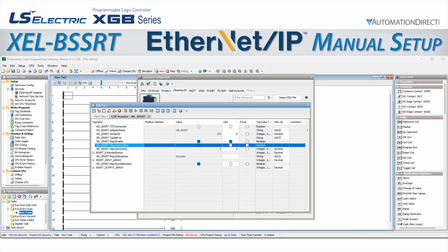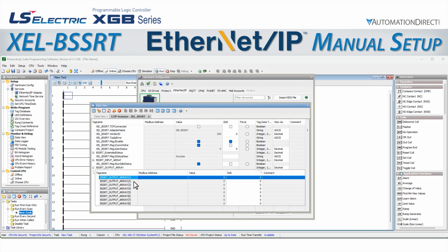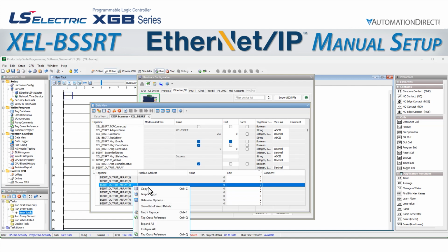We go back to Productivity Suite and maximize our output array. Remember that it's the third address we're looking for, and the productivity software starts its array element number at 1, so we will actually use element 3, not element 2, to control the TN32A. Productivity Suite also has a cool feature to allow us to look at the individual bits within a word. We right-click on the element and select Show Bit of Word Details. It breaks out each bit as true or false.